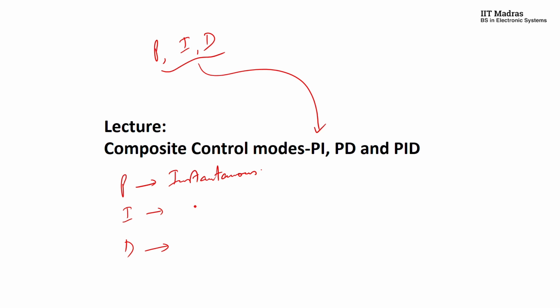When you take an integral controller, this reduces the offset error to zero. And depending on the constant Ki, which is the integral constant, the rate at which the integrator would respond to a certain error curve will be different. If you make this gain larger, then the integral control will be very aggressive, and if it is smaller, then it will be less aggressive. In any case, you are going to get the offset error to be zero due to an integrator.